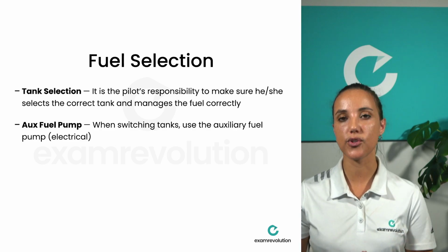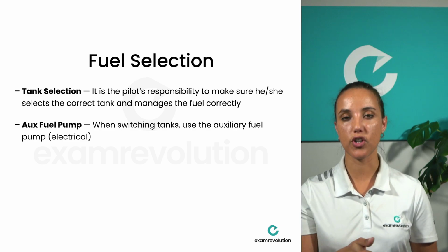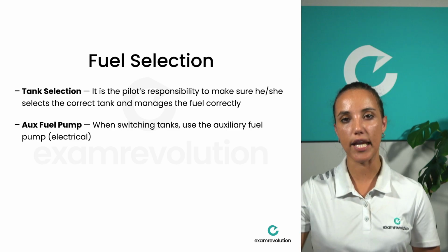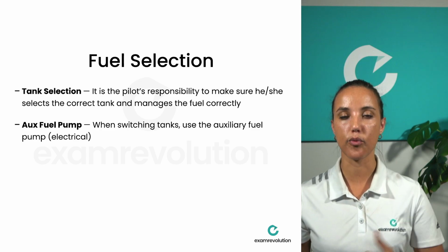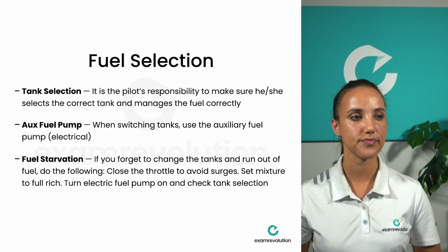When switching tanks, use the auxiliary fuel pump. So you'll switch it on, make sure the fuel pressure is within limits, change the tanks and make sure that the fuel pressure has stayed within limits before putting the boost pump off.